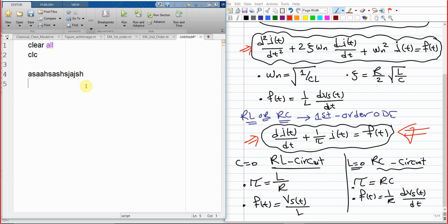With respect to MATLAB, that should be an instruction, so MATLAB will read it and perform something based on what you typed. But if you add the % symbol in front of it, it is an instruction to the person who reads this file, and MATLAB won't see this line. It is like a blank line with respect to MATLAB. You got my point? So this is like giving a comment.